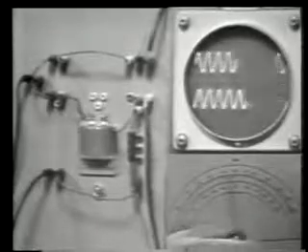As I increase the frequency, though, you'll note that at about 600 hertz, the output starts dropping off. Now we're beginning to reject higher frequencies, which again the low-pass filter must do. Here at about 1200 hertz, you can see that I hardly have anything at all in the output, so we're rejecting these higher frequencies.